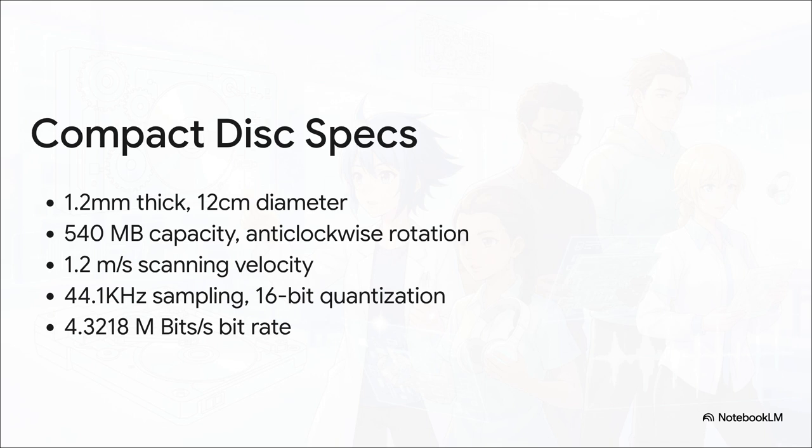To read that, the optical pickup scans at an exact 1.2 meters per second, capturing a 44.1 kilohertz sample rate at 16 bits. When you do the math, that yields a staggering data flow of over 4.3 million bits per second. That's a lot of data flying by.